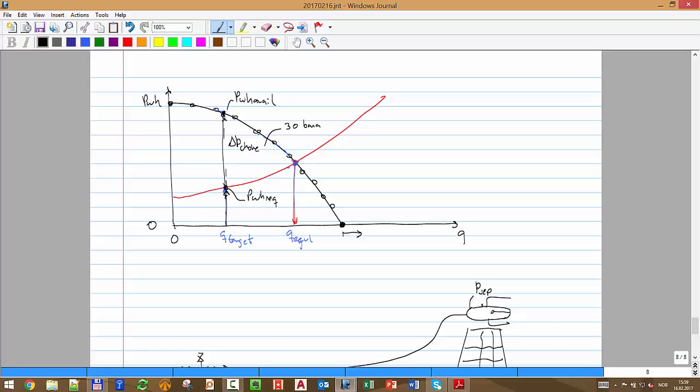Now that we have one more minute, I want to ask you another question. What happens if we want to have a rate higher than the equilibrium rate? In that case, the supply is much less than the demand. You don't have enough energy. So you have to use some device that will do the opposite of the choke, will boost the pressure. For that we have to use a pump, or in our case, since we are talking about gas, a compressor. Remember, pump is for liquid and compressor is for gas.